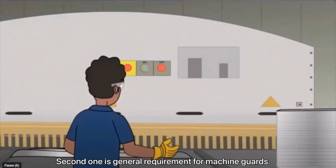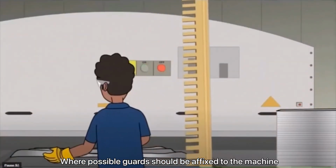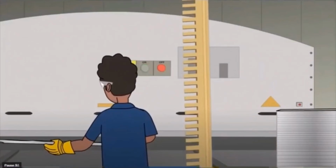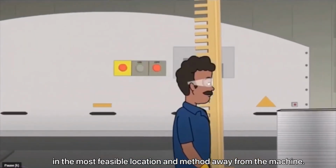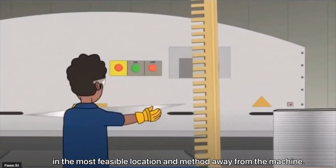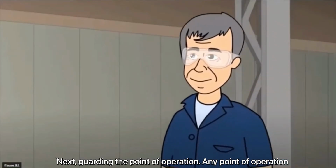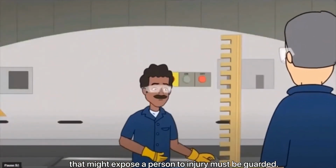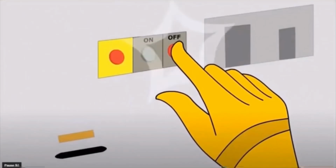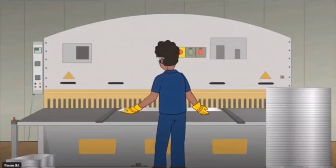Second one is general requirements for machine guards. Where possible, guards should be affixed to the machine in question. When this is not possible, guards should be secured in the most feasible location and method away from the machine. Next, guarding the point of operation. Any point of operation that might expose a person to injury must be guarded. Guarding devices must comply with all applicable standards.